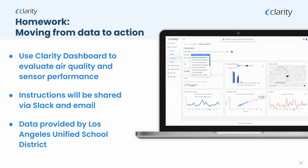So we have a question here from Robert. Can you define the difference between calibration and co-location? Yeah, absolutely, Robert. Co-location is simply the physical placement of the sensor and the reference. So we're just putting them in the same place. Calibration is using the data you got from the co-location to make corrections to the low-cost sensor.